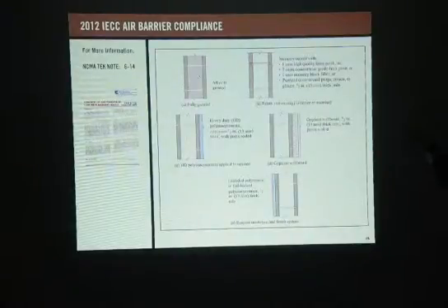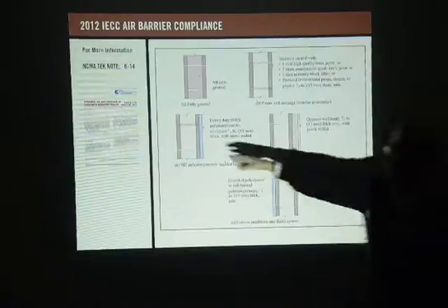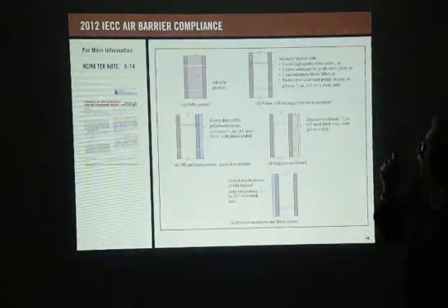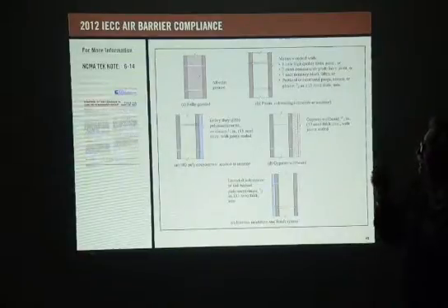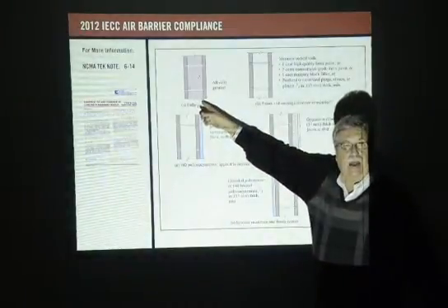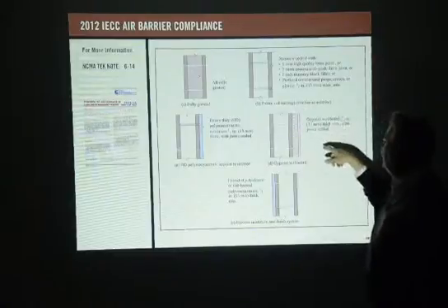These 5 assemblies, again, all come back to what's acceptable as far as the codes. And again, we're looking at the tech note for section C, section 6, the control of air leakage in concrete masonry walls. Do we have that with grout, fully grouted? Yes. Block walls, paints and coatings? Yes.